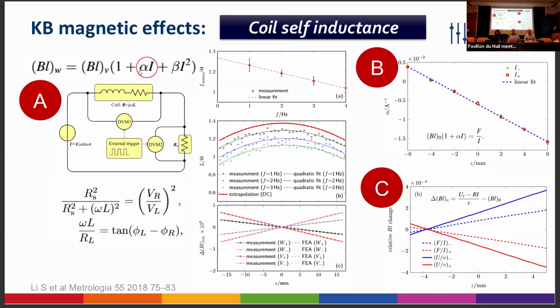Yeah, but how can we measure the alpha? There are several ways. You can do a direct different frequency exponential, right? You use the standard resistor, and you measure the voltage on the coil and the standard resistor and do some calculations to figure out the phase delay, the amplitude, and then you do a linear fit on the frequency dependence, and you can find the DC values.